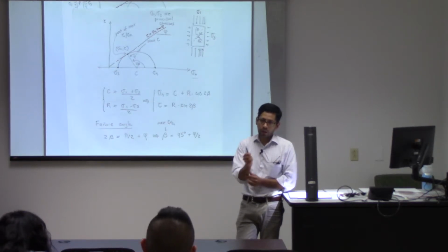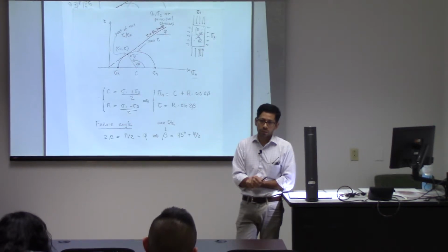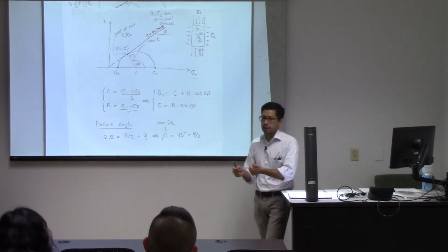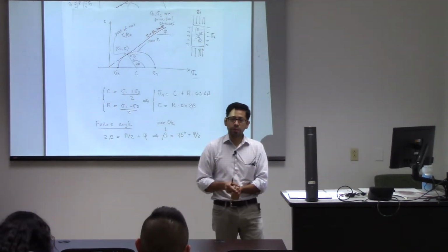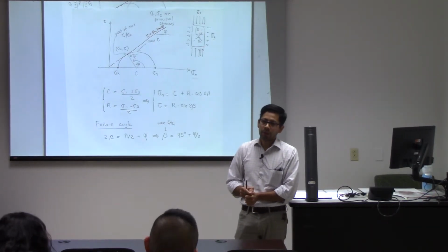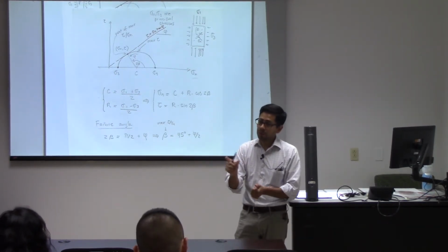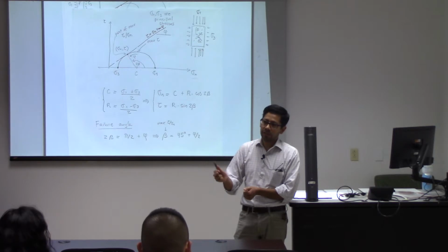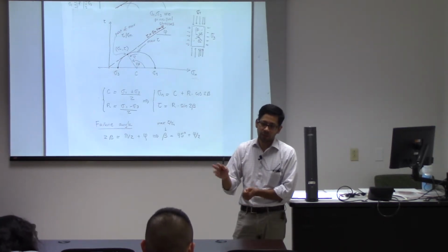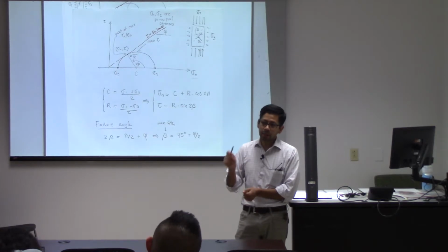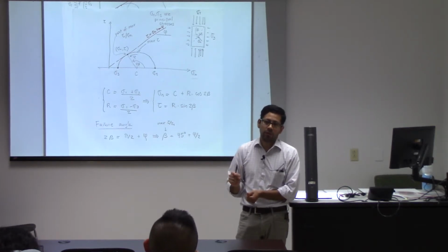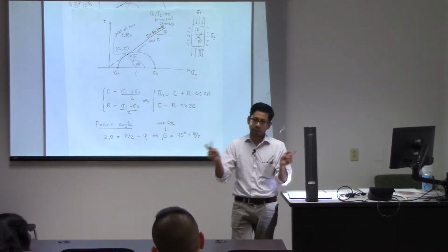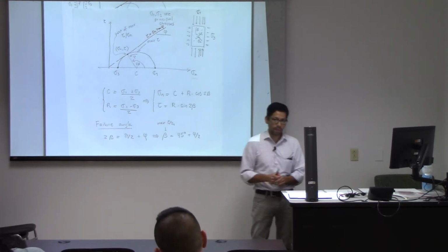Do you have a question, Sky? No? Yes, Mr. Abe: the value for that angle? The friction angle of rocks is typically 30 degrees to 45 or 50 degrees. So if you consider those two numbers, the failure angle is going to be from 60 degrees to 72 or so degrees, more or less. But I'd like you to remember the angle 60 degrees, okay? For a friction angle of 30 degrees, 30 divided by 2 is 15, 15 plus 45 gives you 60, okay?